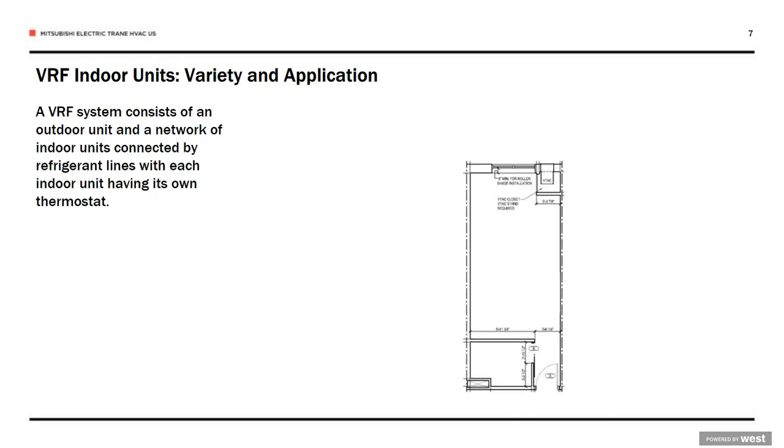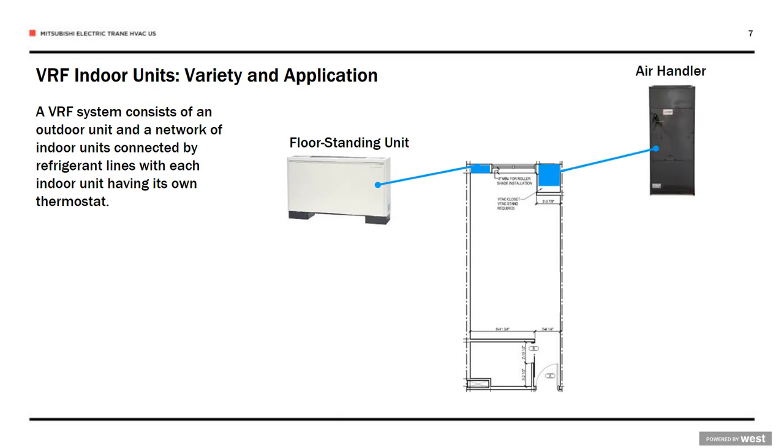The outdoor unit contains the compressor, condenser coil, heat exchanger, fans, and electronic controls. Outdoor units may be used on their own as a single module or twinned to increase capacity to achieve the building's conditioning requirements. The indoor units contain a fan, filtering mechanism, heat exchanger, and controls.